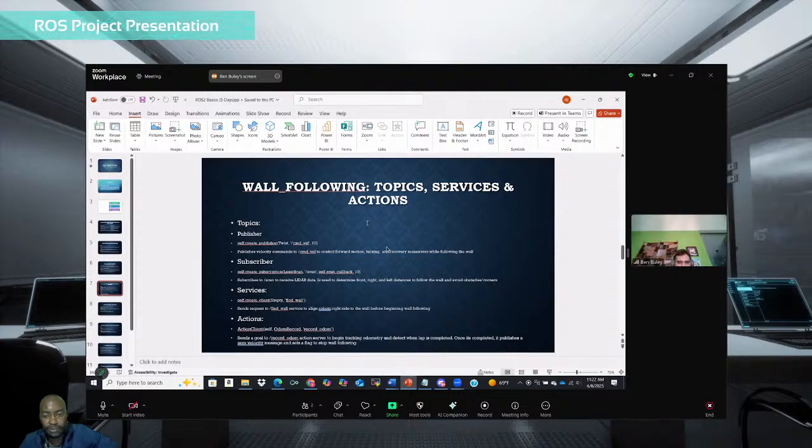So now I'm going to be going through the topics, services, and actions for my wall following behavior. All right. So the topics, here's my publisher, the self-create publisher. It publishes velocity commands to command vel to control forward motion, turning and recovery maneuvers while following the wall. My subscriber, the self-create subscription, subscribes to the scan to receive LiDAR data, and it's used to determine front, right, and left distances to follow the wall and avoid obstacles and corners.